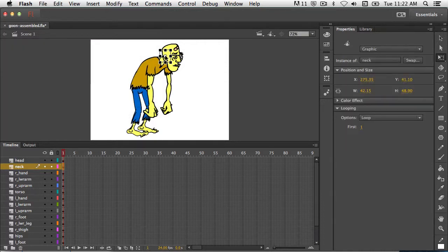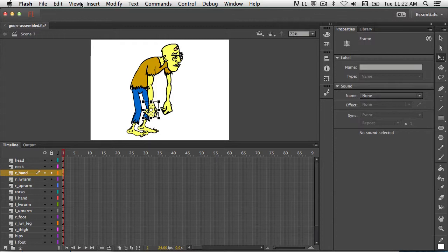And again, I'm going to move these pivot points while I think about it. You want to move the pivot points ahead of time so that you don't have to worry about this down the road. The problem, if you decide to move your pivot points after you've already done lots of tweening, is that your pivot is going to go through a change, so all of your tweens get messed up. So set your pivot points on the first frame anyway. Okay, so I'm just going to continue through here.